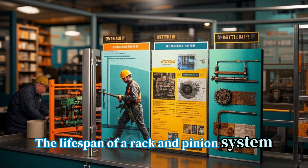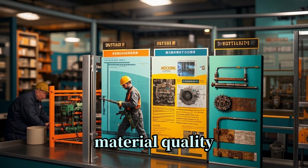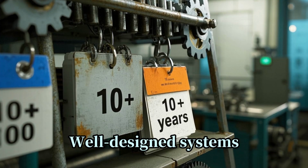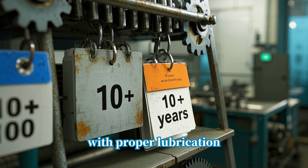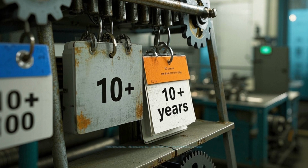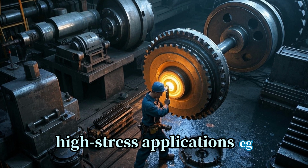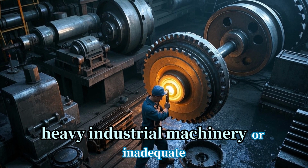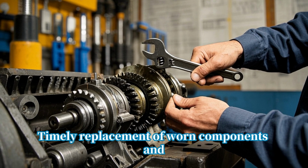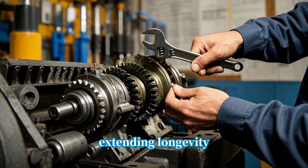Life expectancy of a rack and pinion. The lifespan of a rack and pinion system depends on factors such as material quality, load conditions, maintenance, and operating environment. Well-designed systems with proper lubrication, protection from contaminants, and regular inspections can last 10+ years. However, high-stress applications, for example, heavy industrial machinery or inadequate maintenance may reduce durability. Timely replacement of worn components and preventive care are key to extending longevity.